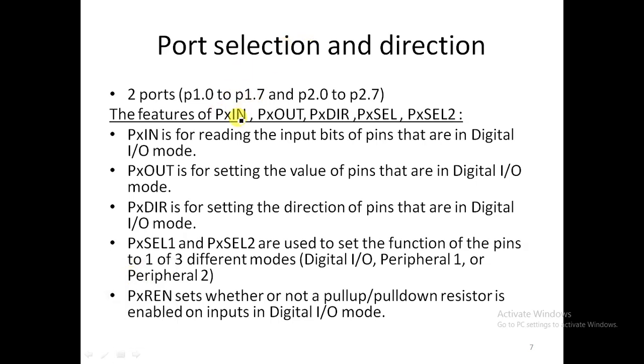If it is the first port, then I am going to write P1. That represents P1DIR or P1OUT. P1IN means in the first port, if any value is taken from outside, it reads the inputs from that pin. So you take the instruction P suffix x IN.